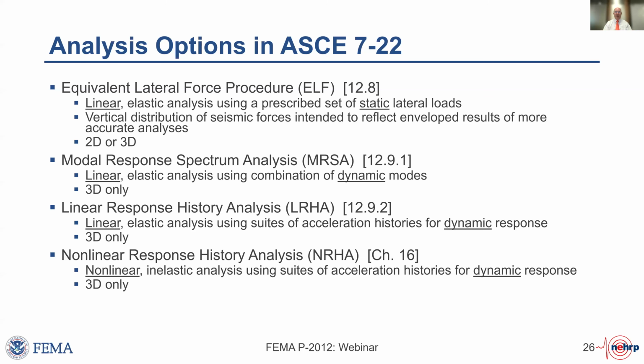The idea is that we're trying to even better understand the dynamic response. So instead of characterizing the demands with a simple response spectrum, we actually think about specific ground motions. It's still a linear analysis though, and it's 3-dimensional. And the strongest tool at our disposal for practical structural engineering is the nonlinear response history analysis method. That method uses ground motions to characterize demands and considers the inelastic response of a building. So, nonlinear modeling. Again, this is a 3-dimensional method.